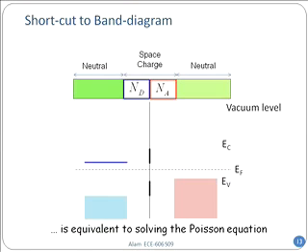The second one is to get to the bulk region, far away from the junction. And you know in the bulk region, if it is N equals ND, then you know where the Fermi level has to be, right? All of you know that. And so therefore, I have drawn the blue conduction band because it's donor. So I'll first draw the conduction band. If it is acceptor, then I'll first draw the valence band. So I've drawn the conduction band in the donor first.